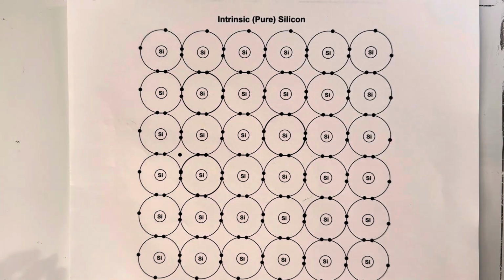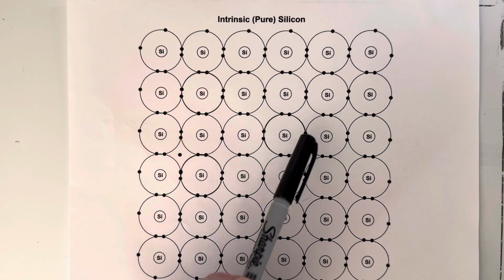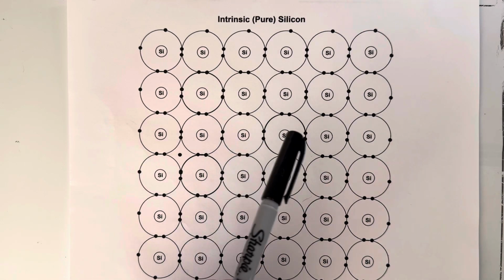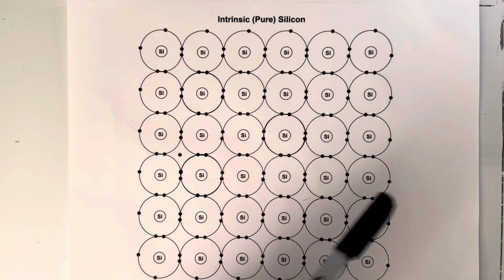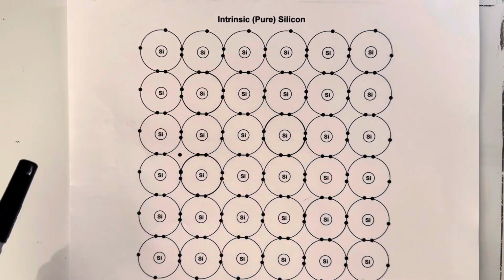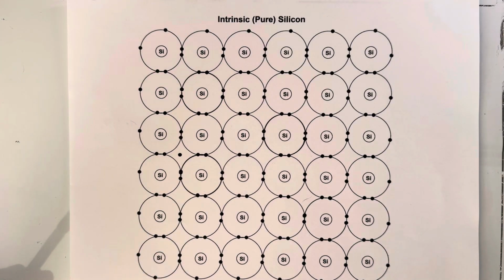Now, occasionally what happens is that since it's not at absolute zero, there's going to be some thermal agitation, and once in a while an electron will get knocked out of the valence band, and that will be available as a charge carrier through the crystal. Okay, that thermally generated charge carrier constitutes a leakage current through the crystal, and we just call that leakage current.